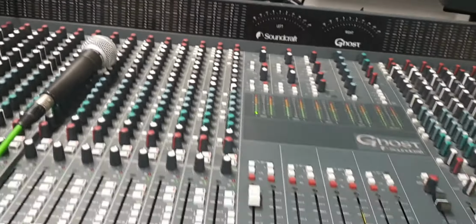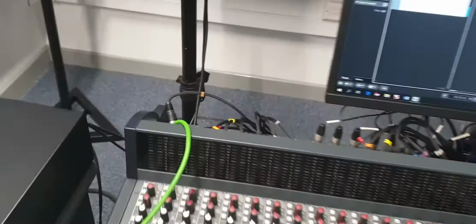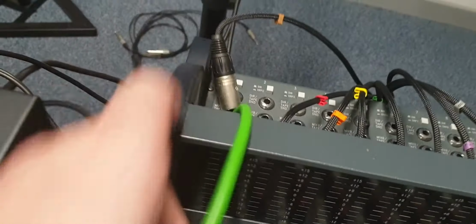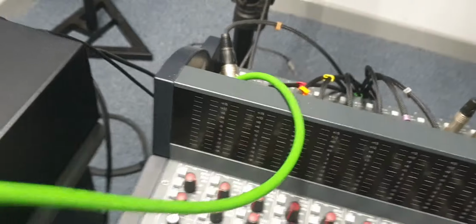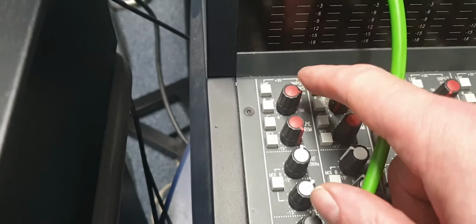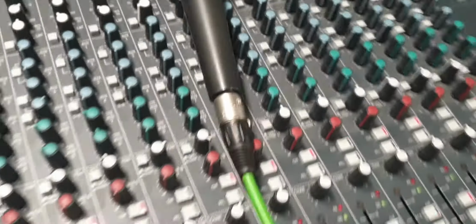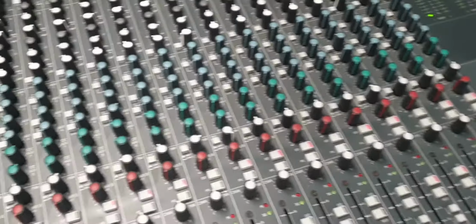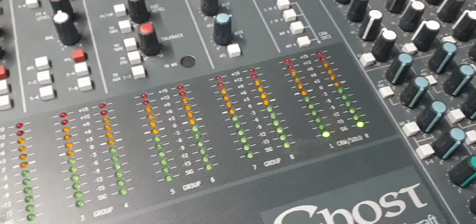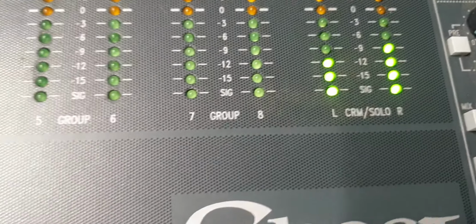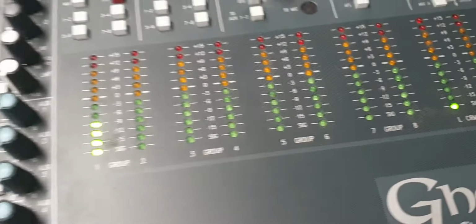How did we get that level? The way that we got that level is the microphone's plugged in the back as we've seen earlier, which just came round the desk. And then we've got the gain control here, and we're going to set that level till we see 0 on this control here. So first off, let's press the solo in and go 1, 2, 1, 2. There, it's hitting just below the 0. Turn the solo off.